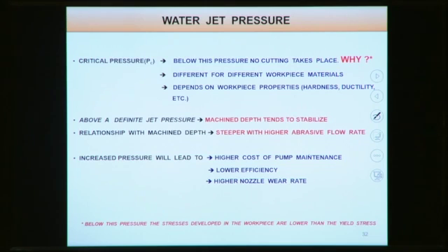Increased pressure leads to lower efficiency, because with the increase in pressure your velocity increases, and these high velocity abrasive particles coming out of the nozzle will wear out the inner surface of the nozzle. So you have to change the nozzle. Increased pressure will lead to lower efficiency, higher nozzle wear rate, and also higher cost of pump maintenance. If you increase the pressure, pump maintenance will be more.